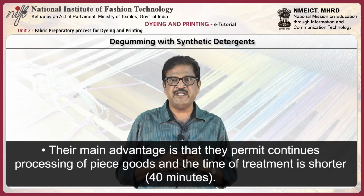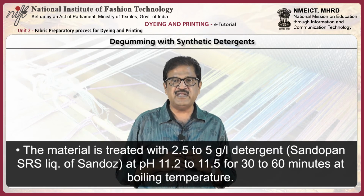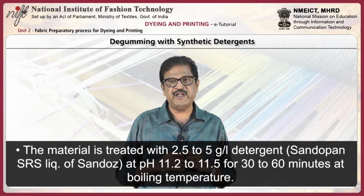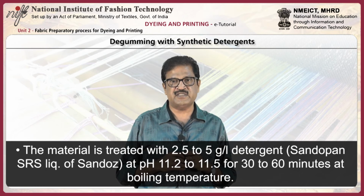Their main advantage is that they permit continuous processing of piece goods and the time of treatment is shorter, about 40 minutes. In this method, the material is treated with 2.5 to 5 grams per liter detergent at pH 11.2 to 11.5 for 30 to 60 minutes at boiling temperature.